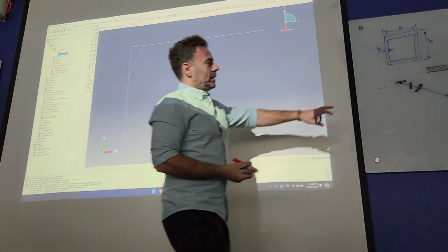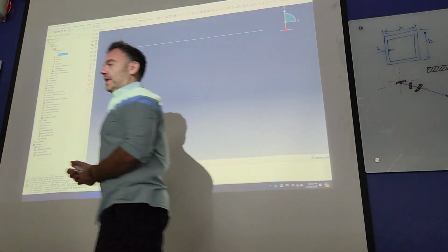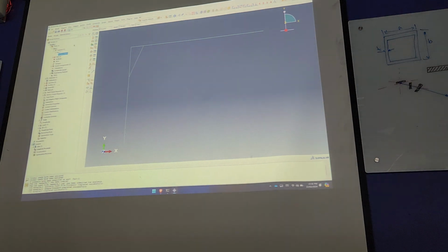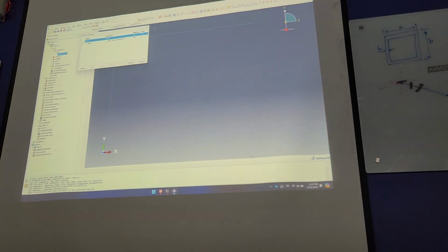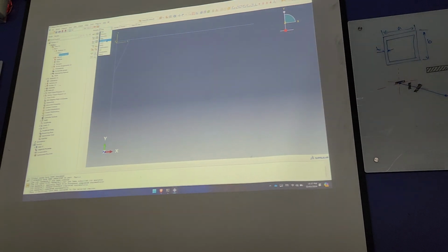To do this, we do beam orientation, yeah? And then that's this button here. I mean, obviously, like you've done it. And we choose our beam elements or beam sections only to assign those beam orientations. And that bit in properties is done. Assembly is easy, just bring one in. Step is just linear perturbation, so nothing new there.